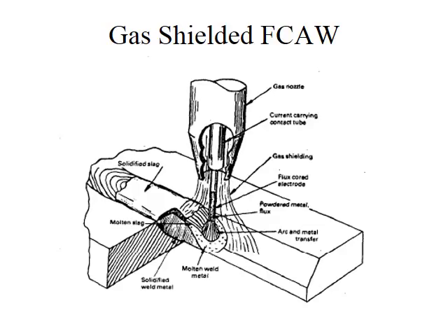You've also got the flux in the interior of the flux-cored wire or electrode, and it's burning off and also providing a slag covering that's helping to shield the molten weld metal as we're depositing weld metal into our weld joint. So that's the main difference. One has an additional gas shielding component to it. The self-shielded flux core process doesn't.